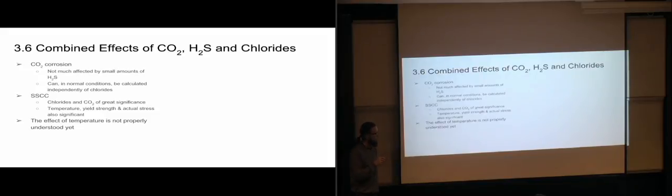And the effects of temperature are not properly understood yet with regards to the combined effects here. So we don't really know if it's better to have a low temperature or a high temperature or something in between. We don't know what's the best option here. What we do know is that 50 to 100 degrees Celsius seems to create a very large sensitivity to corrosion.